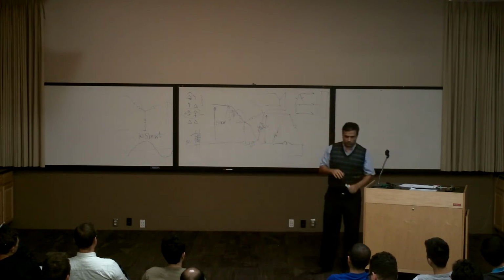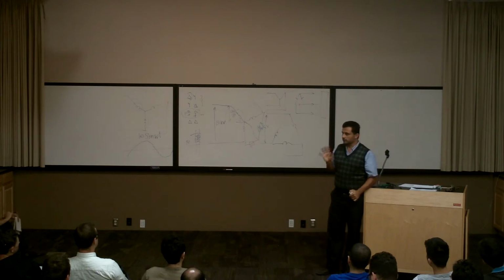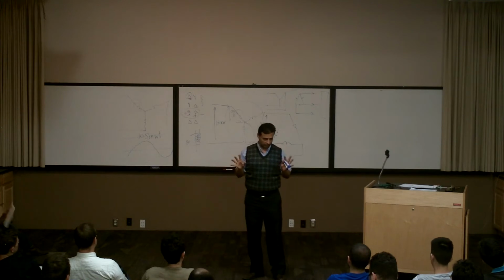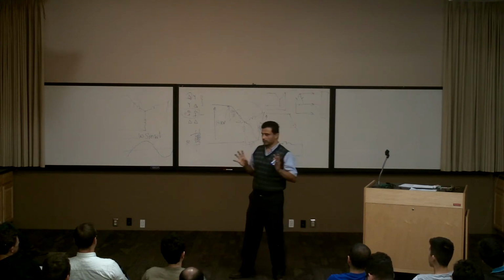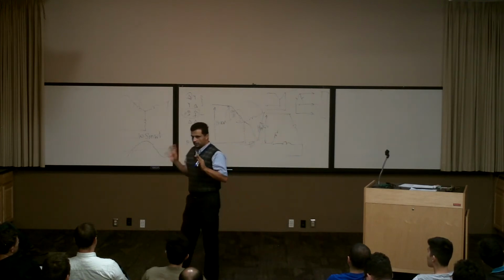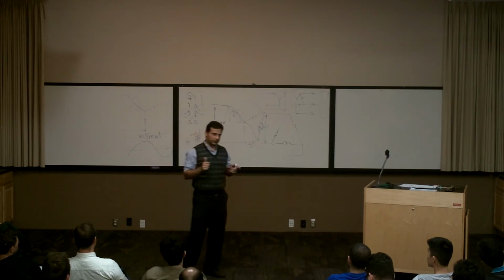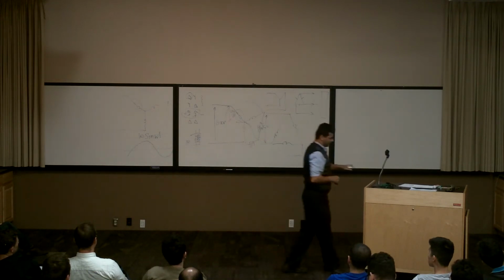In general, if you want to know, the Y connection is used on the high voltage side. It's not always. There are cases where we use delta for the high side, but in general, Y connection, because of voltage isolation, is used on the high side. Delta is a very good filter for the third harmonics in the system.